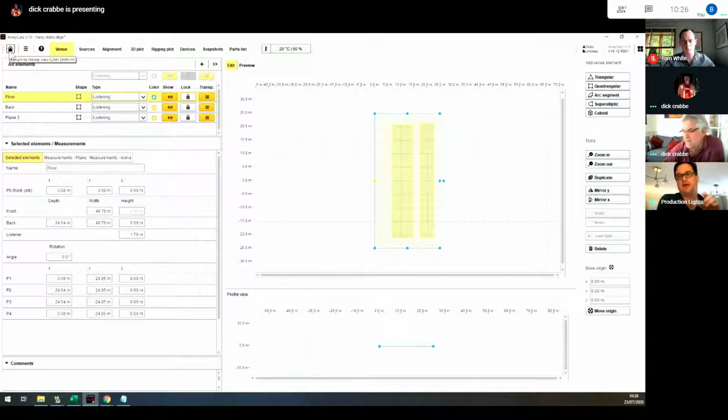So in theory, you could very easily put a load of blocks into your ArrayCalc just to get you going, export into the text editor, go through, and put all your details in. Exactly. Which is exactly the same as out of the CAD programs. You're just using a text editor and not an Excel-based program or a spreadsheet, and then just drag it back in again, and they're all in position. Yeah, exactly that. That's powerful.